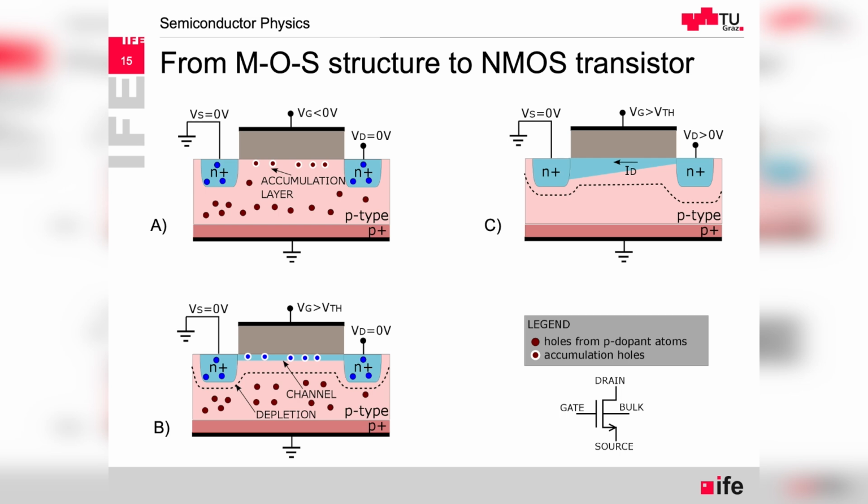And we have normally the inverted charge as we will be going through this calculation. And on the right-hand side, we have the drain voltage, which is higher than the substrate voltage. And so the voltage across the gate towards the drain region, the difference in the voltage, is much lower. And as long as the difference of the voltage is still above the threshold voltage, we have the inversion channel.